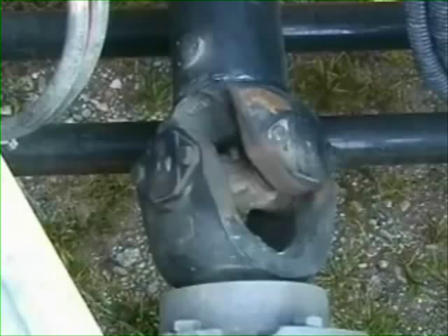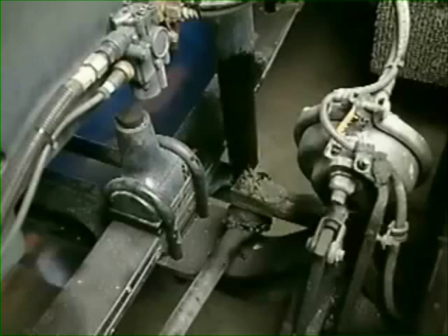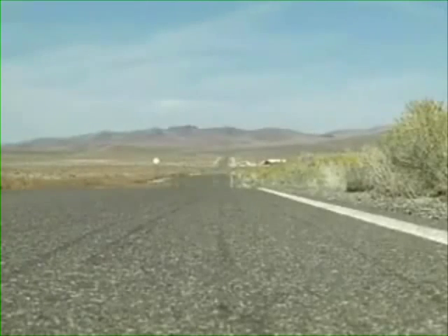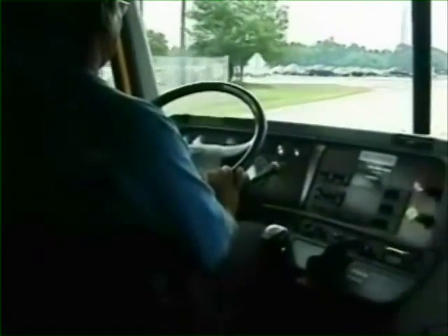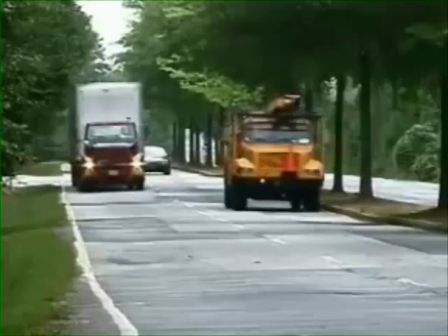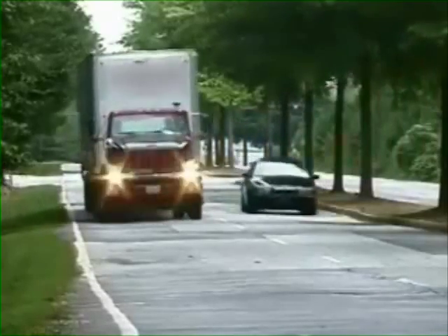If it continues, then check the drivetrain components, rotating assemblies, suspensions, and mounts. Also on a smooth road, check for speed sensitivity. Does it occur at one speed, under acceleration, coasting, braking? Is it continuous, or does it phase in and out? Next, try driving on a rough road. Does this surface initiate the vibration?